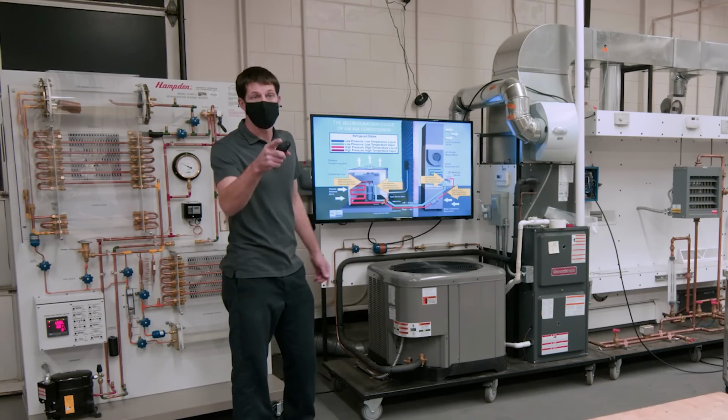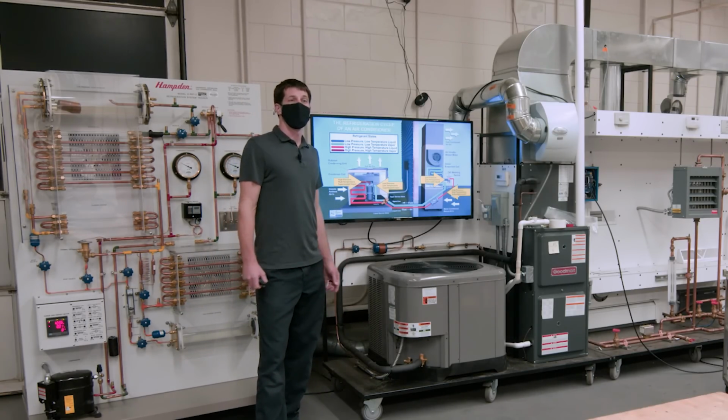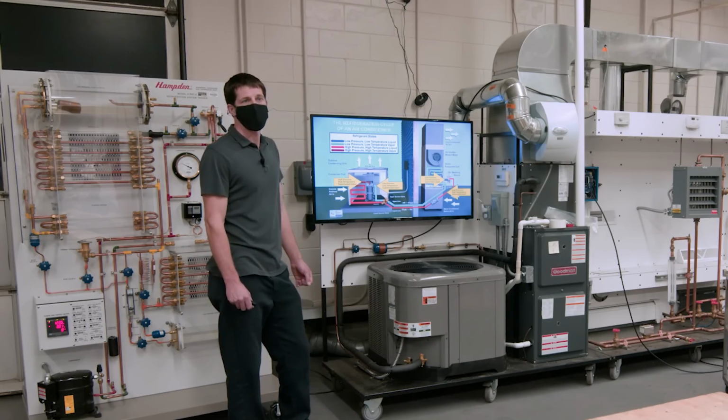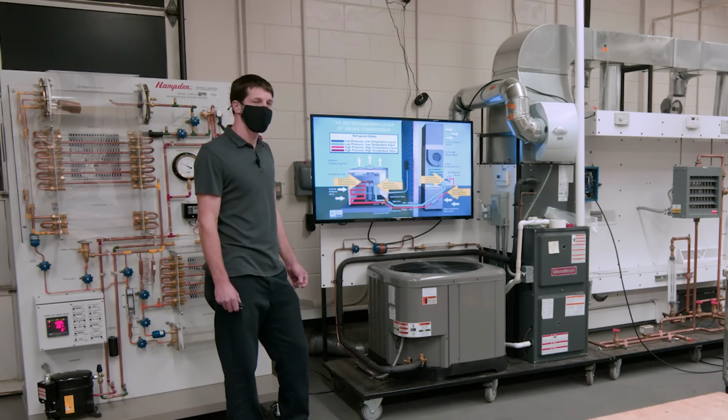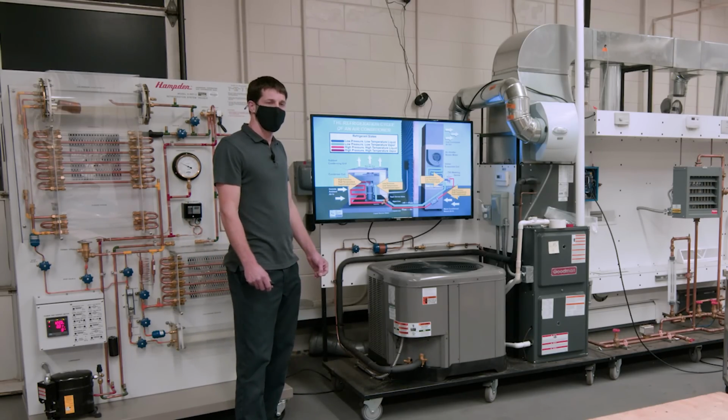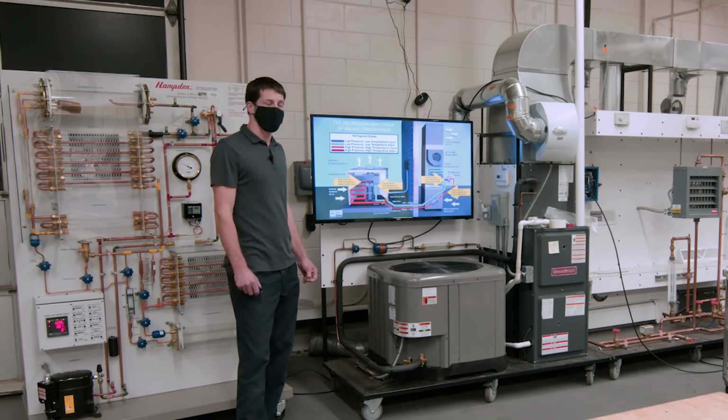And that's a key thing to consider, is that your TXV or your electronic expansion valve isn't just valuable when the system is running under normal conditions. It's also really helpful, the fact that it can go more wide open when you're in a hot pull down or when you're trying to bring the space down to temperature, which is also a nice thing.